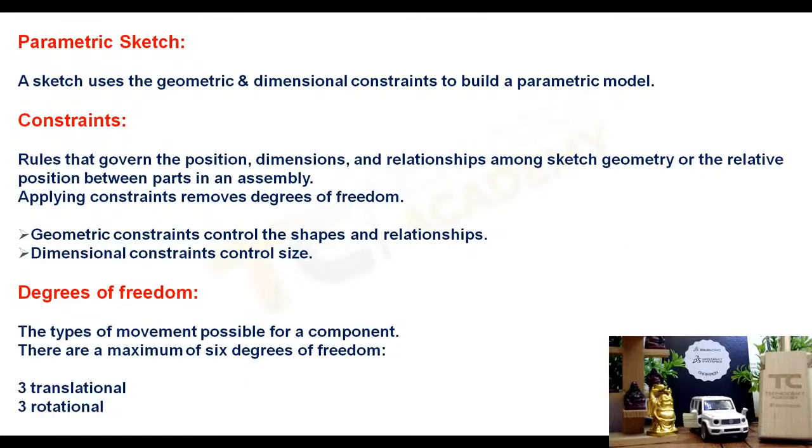Is it a fully constrained or a fully parametric model? No. If you only have the geometrical constraints, it cannot be. You need to define the dimensions for that. Let's say I'll define 50 mm on the bottom longer length, and for the width, the height, I'll define 25. Now I need to constrain that to the axis origin 0, 0. If I specify that, then that particular sketch will become a fully constrained parametric sketch. Very important. Yeah.